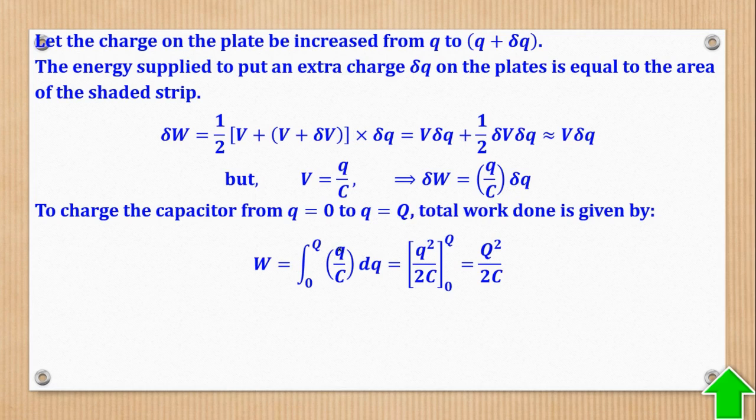So when I integrate this Q, I'll come up with a half Q squared. So this is a half because of the 2, then this is Q squared, but there's also a C here, so it will remain there. I'm integrating from 0 to Q, therefore substitute capital Q where there is small q to come up with this, minus substitute 0 to give you 0, so it would be this minus 0, but it's okay not to put this minus zero because it remains the same. That is why I'm only putting this as the output of the total work done.